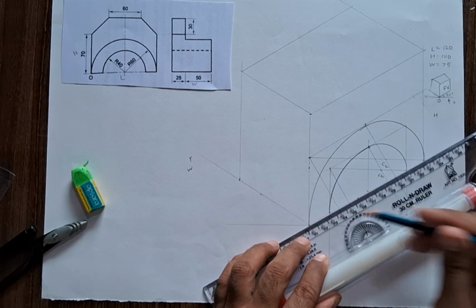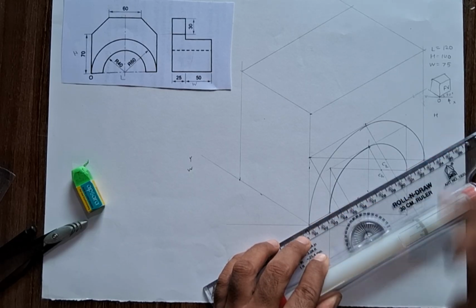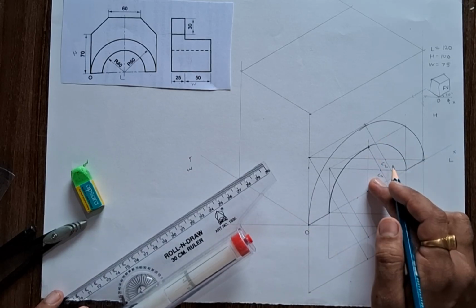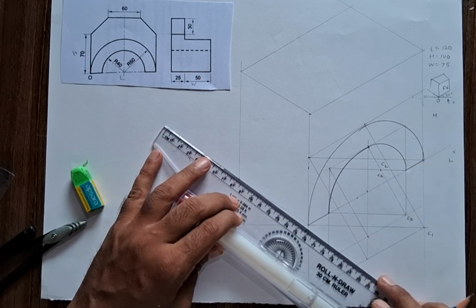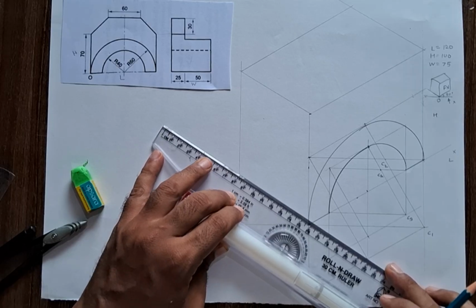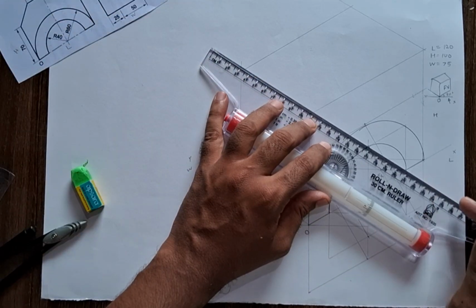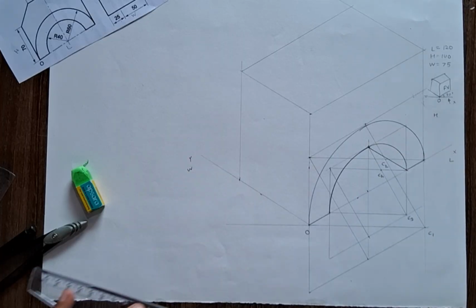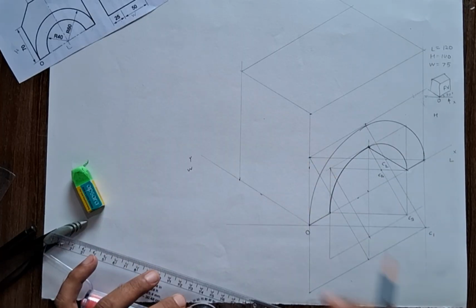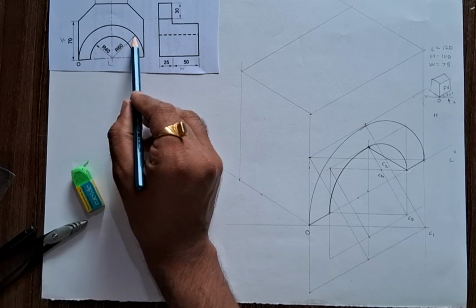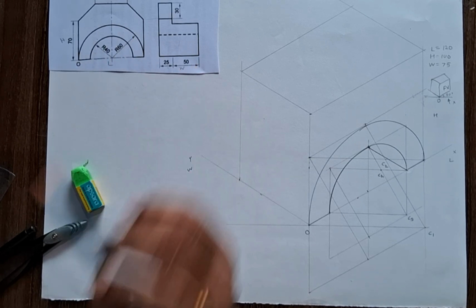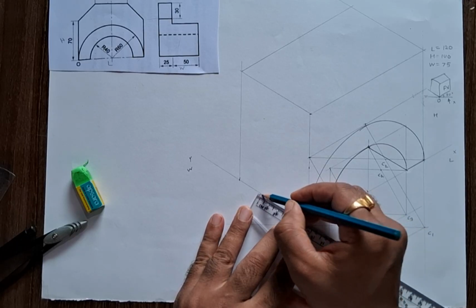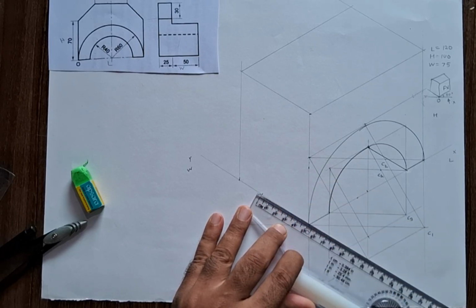So this line is visible in the front view. Now this circle, its depth is throughout along the width direction. So adjust a ruler along the width direction and draw a straight line going in the width direction. Now you can see here the upper half circle, its width is 50 mm. So from O, mark a 50 mm width. This is 50 mm, and